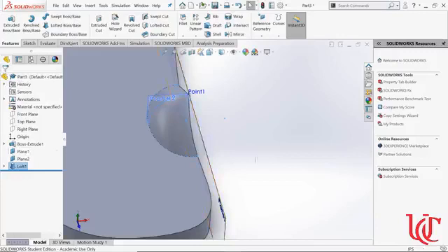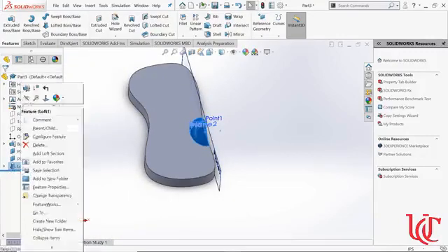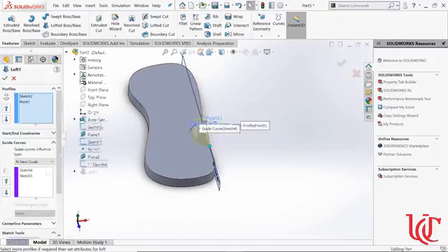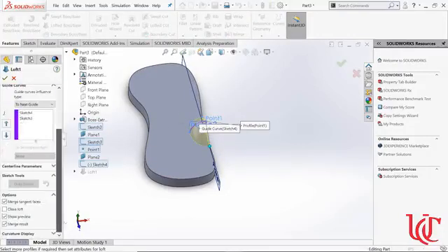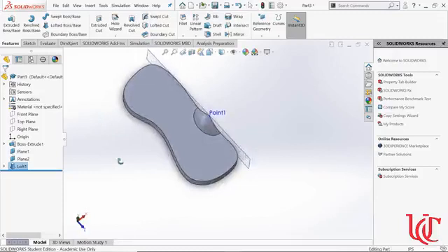Okay, all done. Here's my 3D shape. Now, when I make that loft, I forgot to say that you can go back in and say Edit Feature. Since I already had a 3D shape, I had to select Merge Result to make sure they're both solid. That's normally the default, but you do want to make sure that is selected. You want them together.